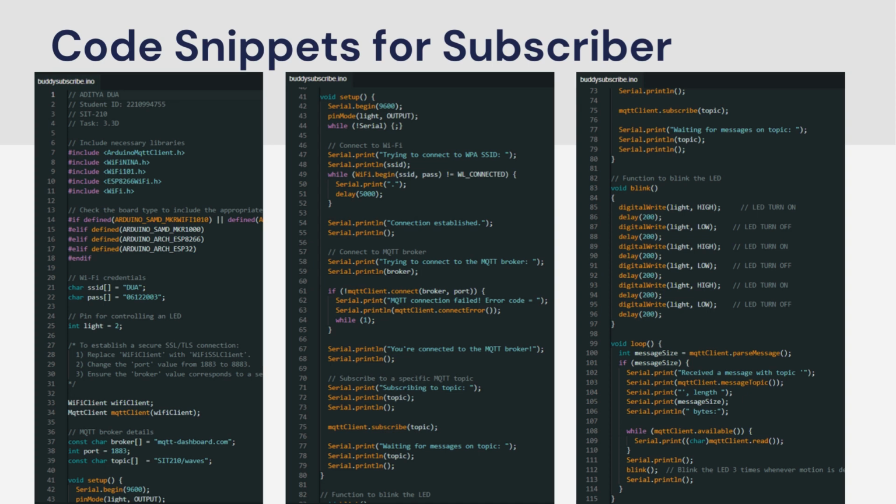It starts with including necessary libraries which are required for working with Wi-Fi and MQTT. Depending on the type of Arduino board, the libraries that are included are ArduinoMqttClient, WiFiNINA, WiFi101, ESP8266WiFi, and WiFi.